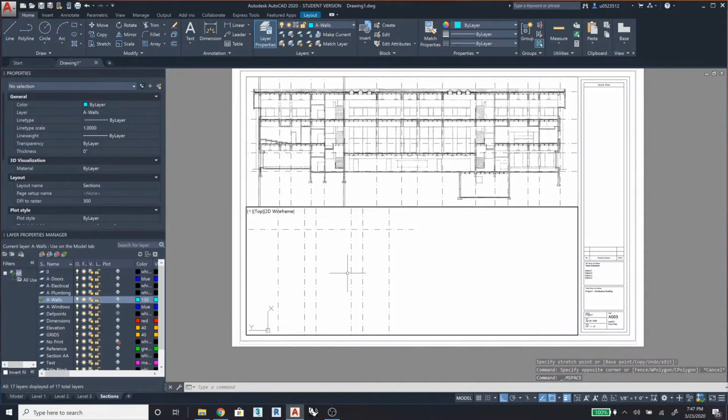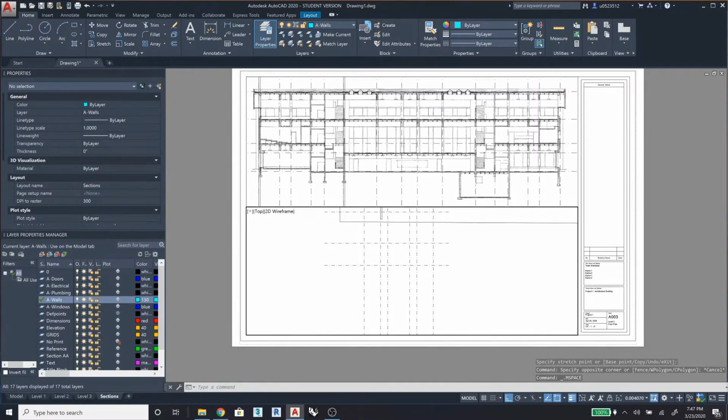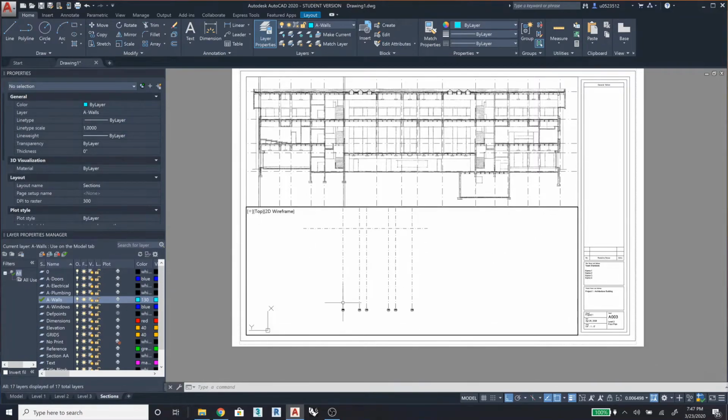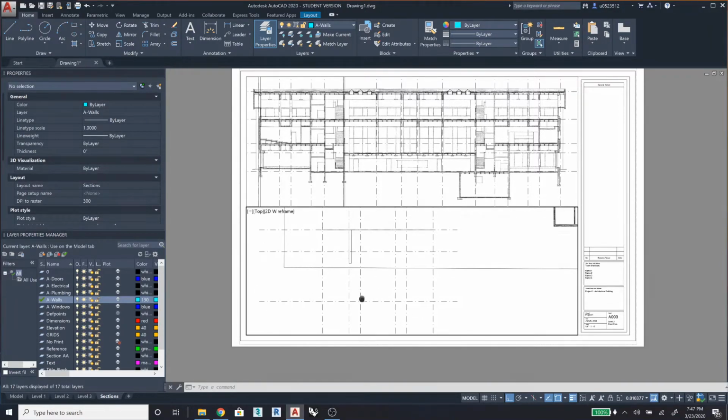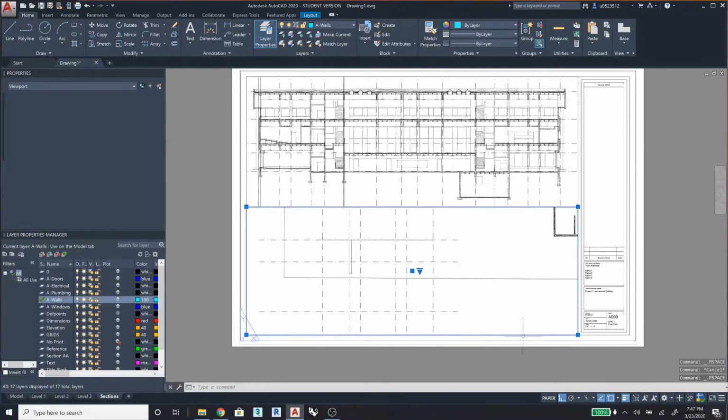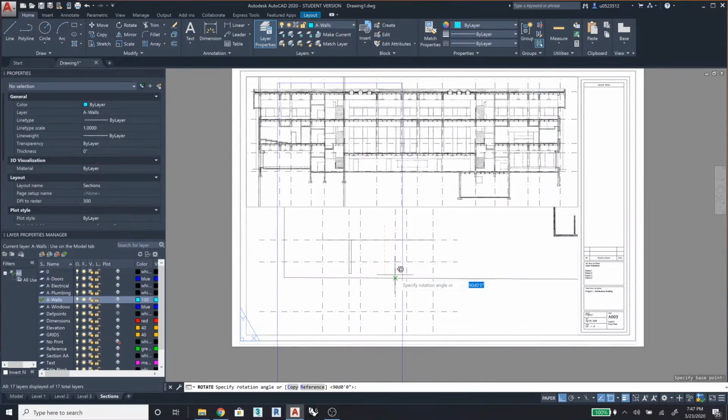Double clicking to enter into model space so I can find my view again. Now see, I'm upside down. I want this to be at the top. And I'm going to have to rotate my numbers as well. So I'm upside down. I'm going to go out to paper space, grab my viewport, rotate the other way 180 degrees.